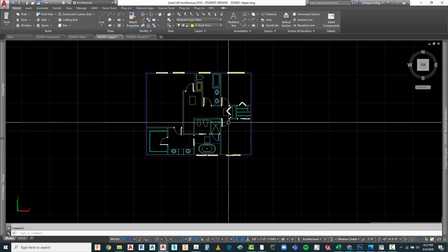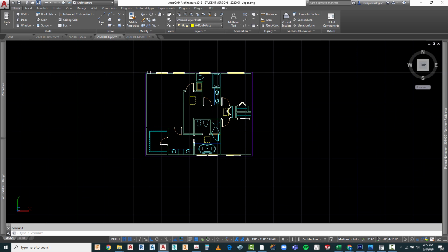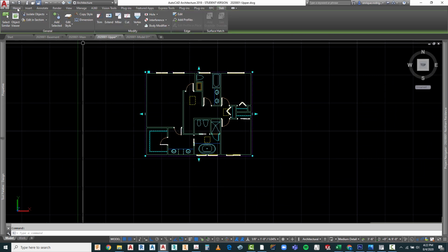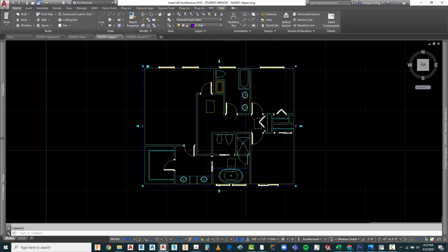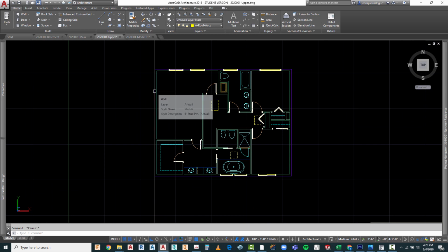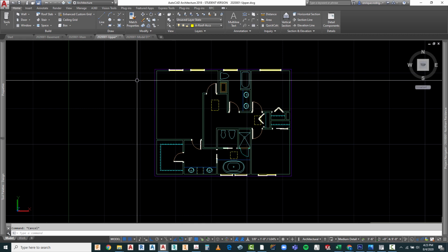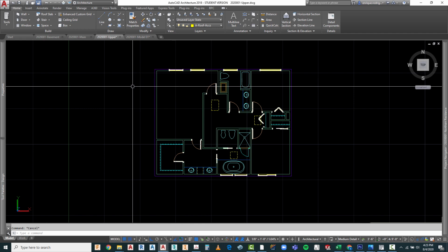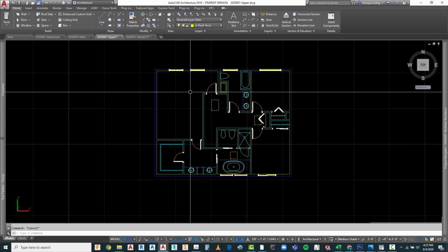So what we want to do with this upper level is going to be extremely easy. Now, if you took a look at the slab, when I click on the slab, it created its own layer, A-slab. So that works for whether it's a wall, A-wall in AutoCAD Architecture, a slab, A-slab, and it's also going to work for the roof, A-roof. But there are two types of roofs that we deal with. We're going to start by drawing one element roofs, which is the A-roof.